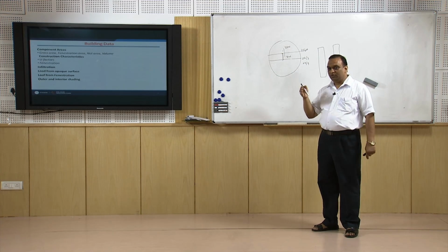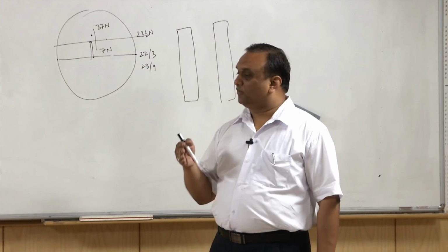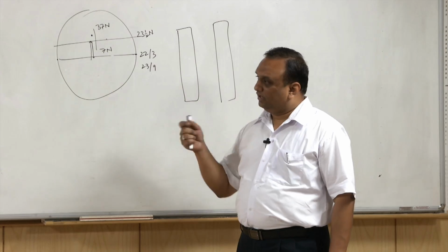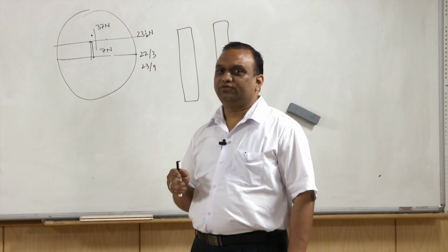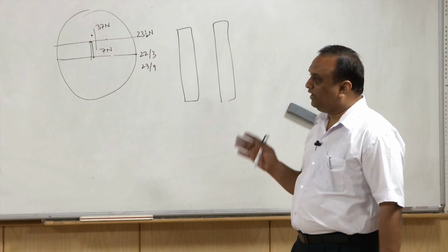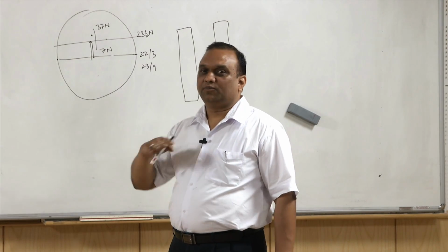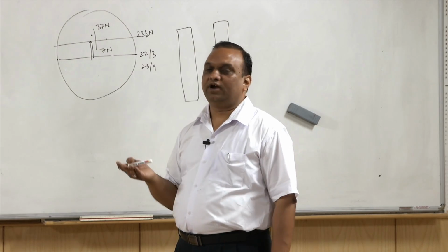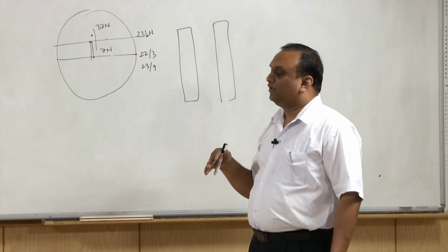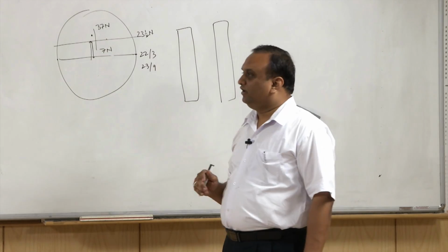Suppose we want to reduce solar load in a house, proper curtaining, thick curtains can also reduce solar radiation coming into the house. There are many ways of passive techniques, they are known as passive techniques, which can help us in reducing loads in the building. Suppose you have a rooftop garden, because most of the heat comes from the roof. A rooftop garden will also reduce the heat transmission